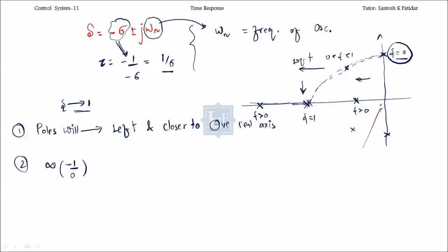Over here this is t equal to infinity. Then it's going to reduce. Over here, again, for this also I'll get infinity. Correct? No, for this it is not infinity. For this, the time constant will be 1 divided by (zeta omega n minus omega n square root of zeta square minus 1). Correct? This is for the overdamped.